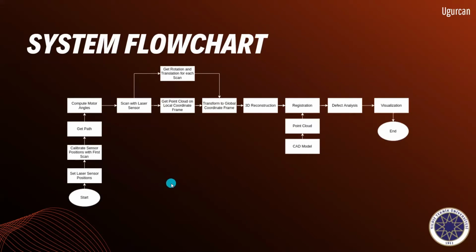First, let's look into the system flowchart. The motors in X and Y axis start to function in a predetermined mode until both limit switches are triggered. This sets the 0 point for our scan. For orientation of the laser, data gathered from the laser itself will be used. A special path is needed for each unique part to be scanned, so users should determine the path to be followed by the laser. The laser starts its path and begins transmitting data to the computer.